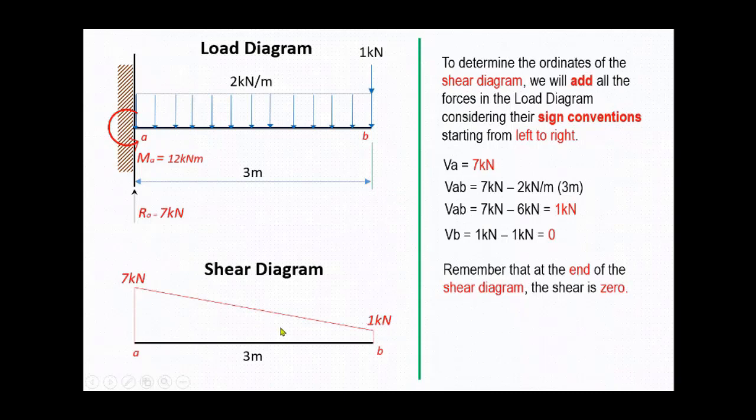It is also the same in the shear and moment diagram. If you have a first degree line or curve in the shear diagram, we will expect a second degree curve or line in the moment diagram.